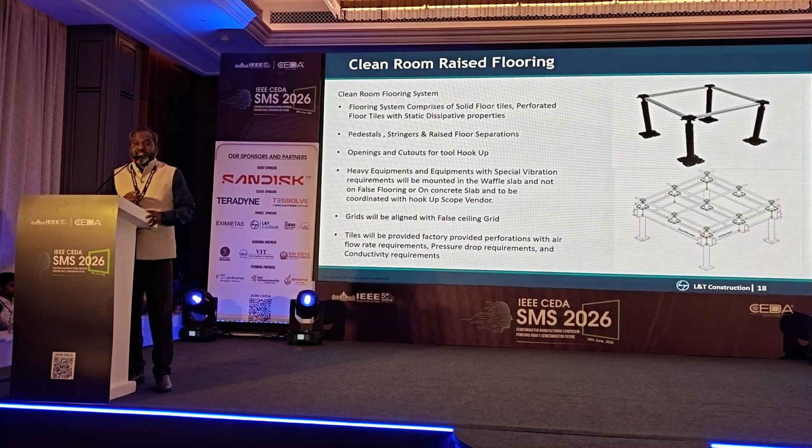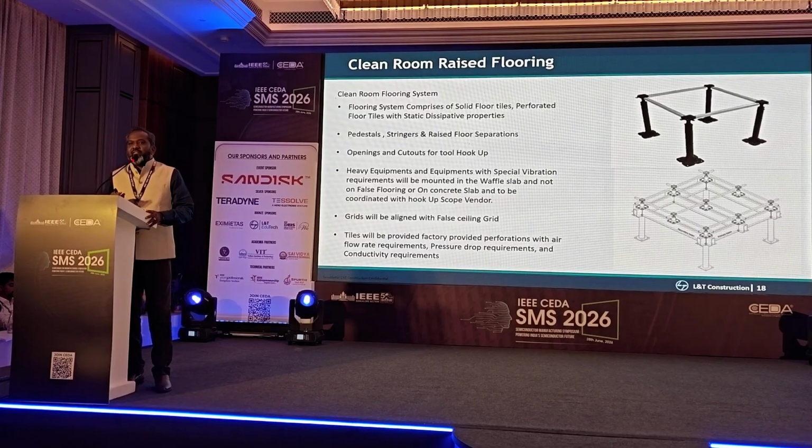And this needs to take about 2 tons per square meter load. Usually a multi-level car park or a driveway is about 500 kg per square meter. So it is 4 times higher minimum of the floor load that it should be able to take.